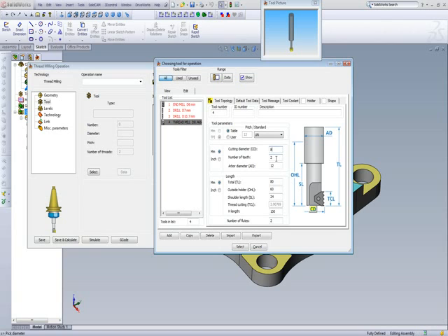This will actually control the amount of times it steps in, as we'll see later on through the part itself. We have our arbor diameter and the rest of our values as well, and we also have our shoulder length. What's important in the shoulder length is that the shoulder length must be larger than the actual depth of the hole that we'll be using.